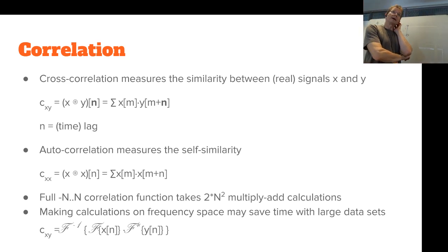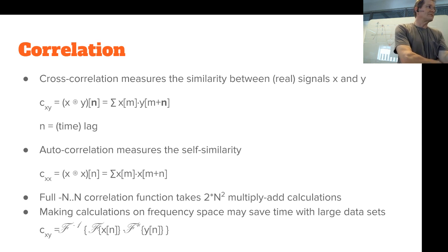Correlation is a simple mathematical operation you can use to find similarities in signals. For example, in radar technology, you send a short radar pulse into the atmosphere. And then it returns back, and you have some really fast processing units that compare by correlation the pulse that was sent and what was returned. It is very effective at removing all the noise components other than those which are exactly the same as the returning signal or the sending signal.